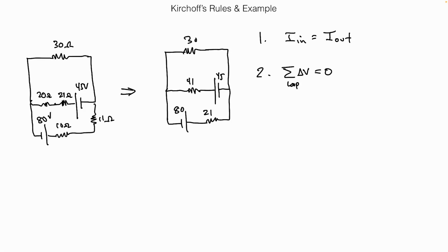It's written in electrical terms, written in terms of voltage. So has anybody figured out what the first rule, the junction rule, is? It's conservation of blank. Fill in the blank. It's the other conserved thing that we have learned about in this class, pretty much day one. Charge. The junction rule states that you can't make charge out of nothing. Whatever charge per time flows into a junction has to equal the total sum of charges coming out of that junction. If it isn't, you've lost a charge somewhere, and that's not good.